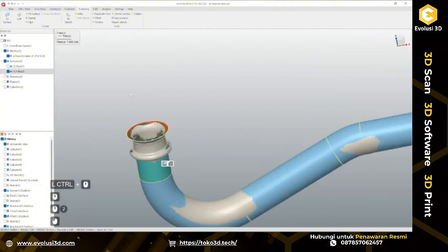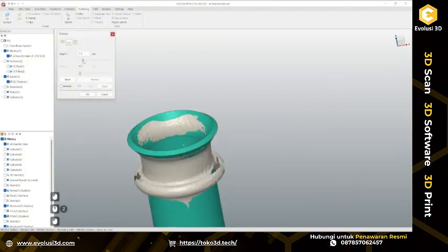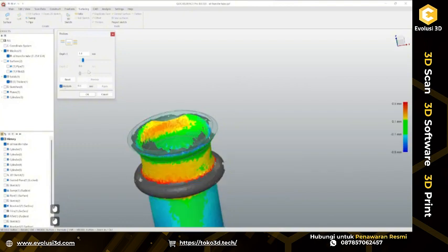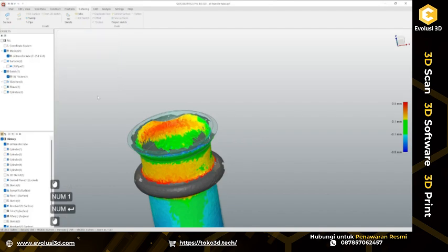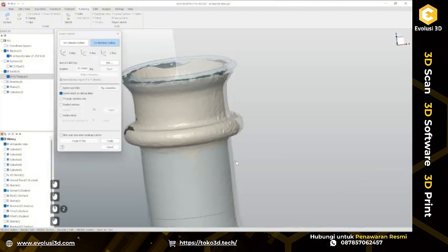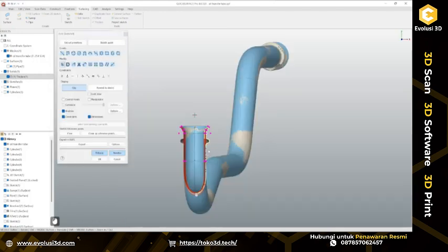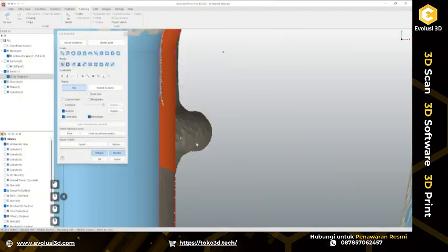Okay, good. So from here, basically, I think the next step would probably be to thicken it. And it should be around 1 millimeter wall thickness for this part. Okay, good. And now one of the last steps is to create, well, how to call it, a mounting flange or just a step up lip so the fitted o-ring doesn't slip too much on this pipe.